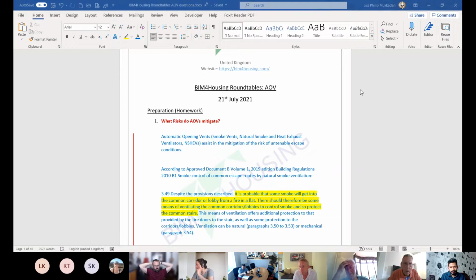If you're looking at that, the fire risk assessment would say that shouldn't be stored there. The fire risk assessment is not linking that to the AOV, and it should be. The fire risk assessment should take that into account, that yes, the issue you're going to have with risk is smoke within the escape routes. The other risk of that is that smoke is not going to be extracted through an AOV, and therefore the two are inextricably linked, really.